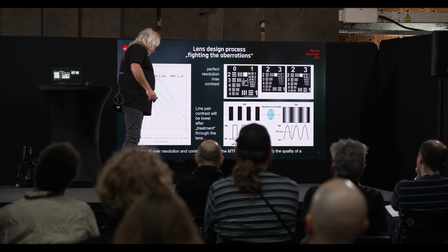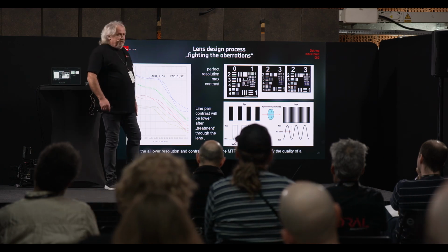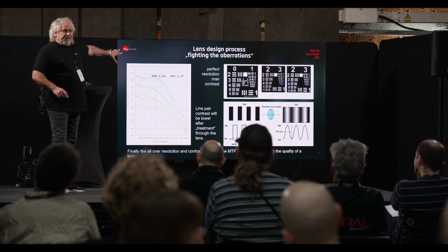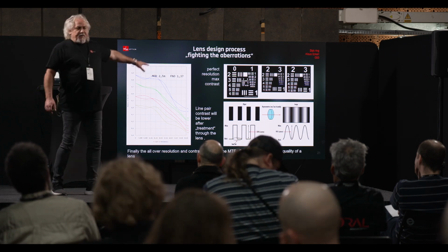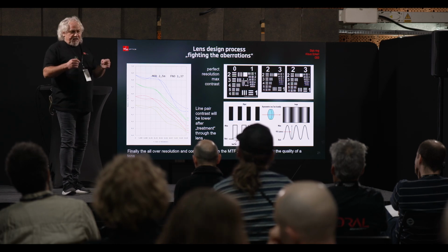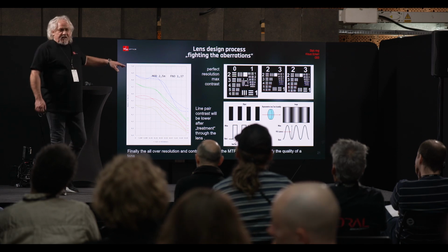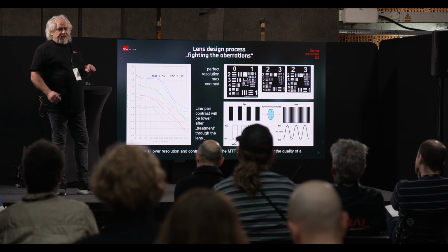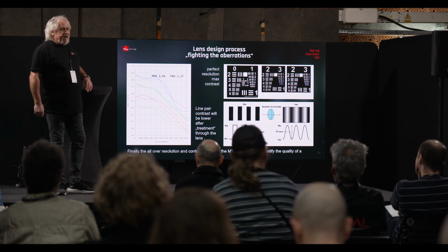And I can tell you when you have around 40 lines above 60, 50%, it's quite good. You have your image. 5 lines per millimeter is quite good for this tremendous big lens. This is rather complicated mathematics behind it. By the way, we have set up a machine for measuring and adjusting all these things in our house because we finally adjust every lens with this technique. We look at any lens finally on these parameters and always adjust a minimum of 2 compensators to get the best balancing.